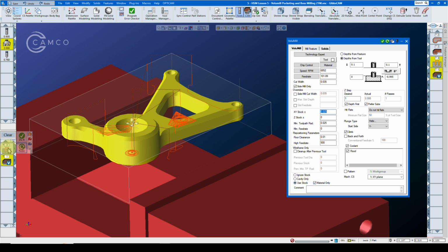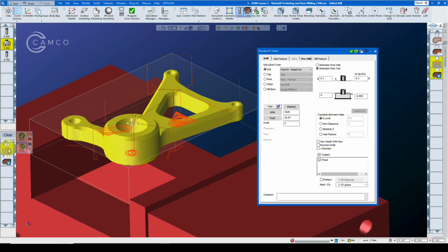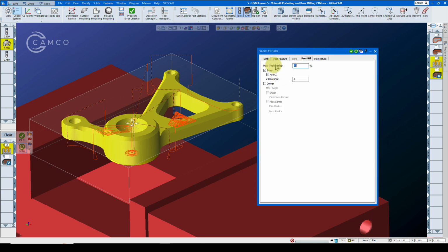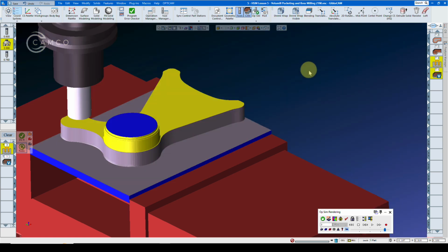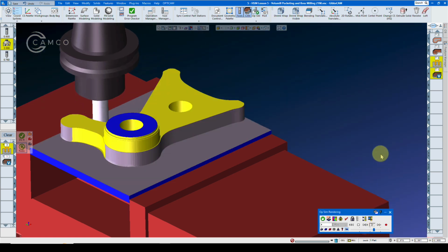You'll notice that we have a drilling process combined with the VoluMill process. It will go into any cavity and pre-drill a hole automatically, matching the Z-axis height of the VoluMill process. Let's step ahead and watch the VoluMill process now that the step is almost done.